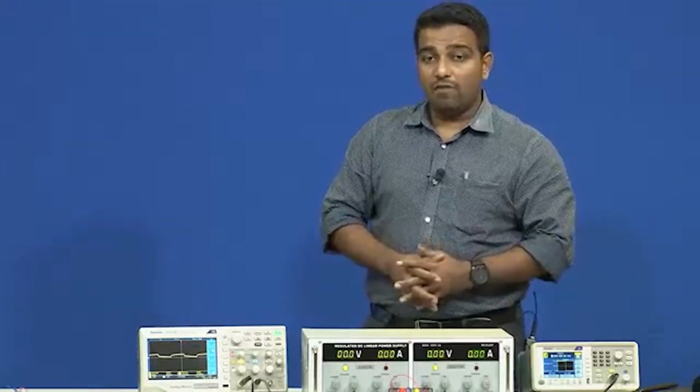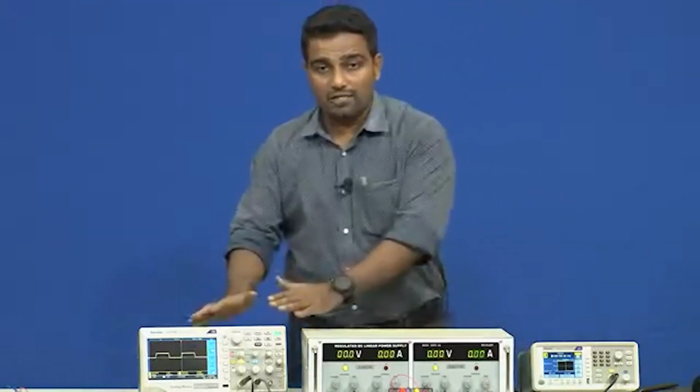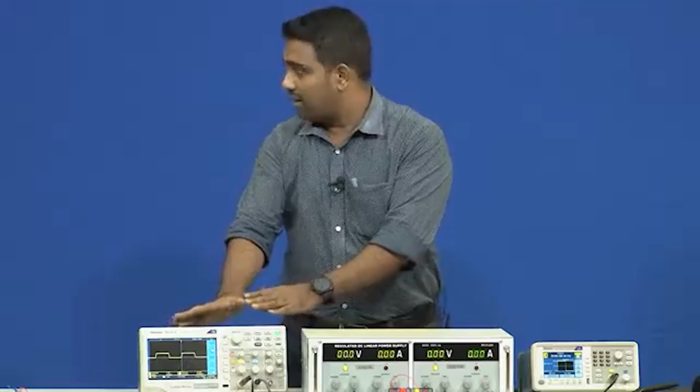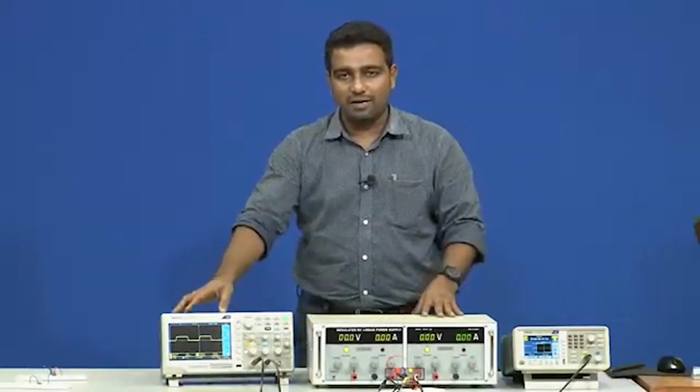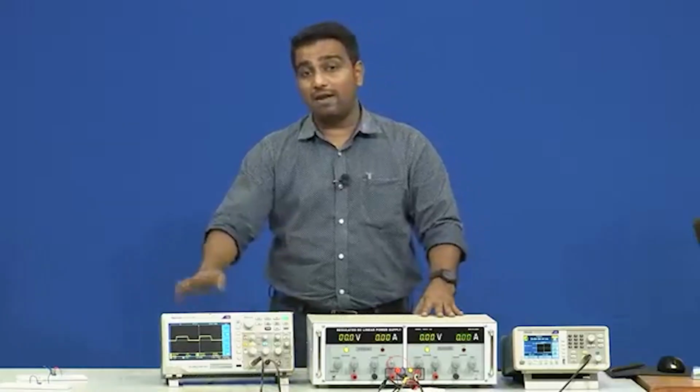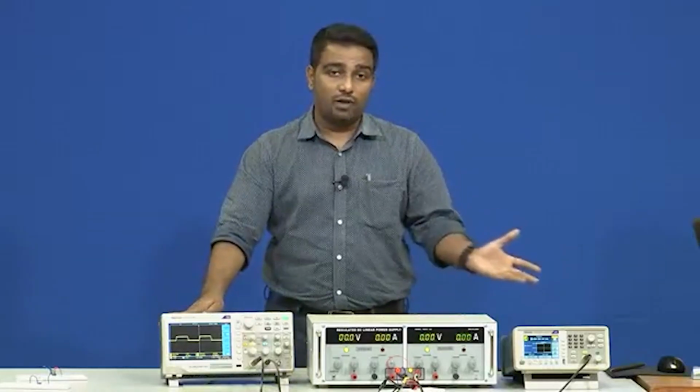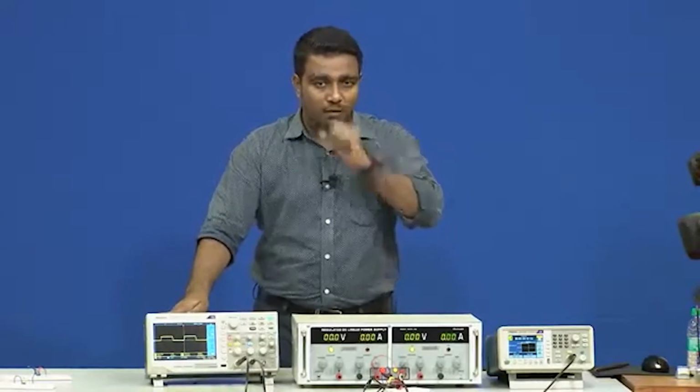Alright. So now, if we know the change in the voltage, that we can understand using the oscilloscope, right, and then we see the change in time, that is delta t. So delta v by delta t will give us the slew rate. So, it is very easy.